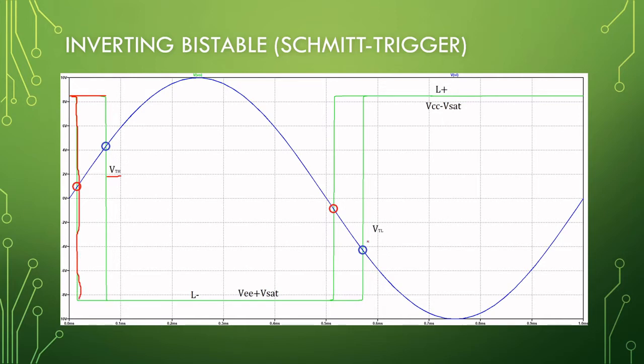That low state will tell the amplifier what the new trigger level is. So this signal at the input can go almost anywhere upwards, but the moment that it breaches the lower trigger point here at minus 1 volt, the amplifier will switch again to a high output state. So the trigger level is back to the high trigger point. It will jump between the high and the low trigger points.